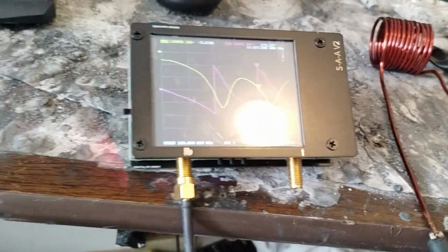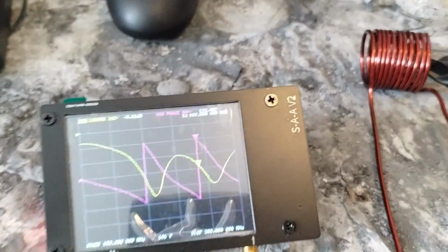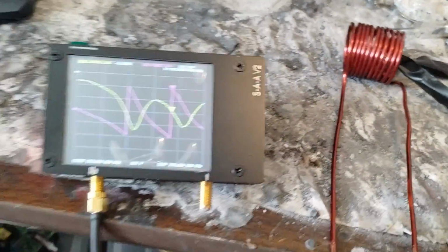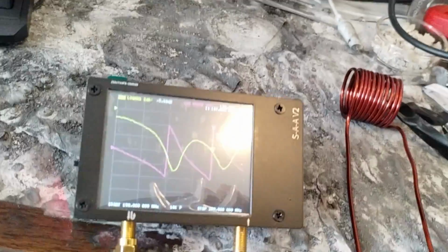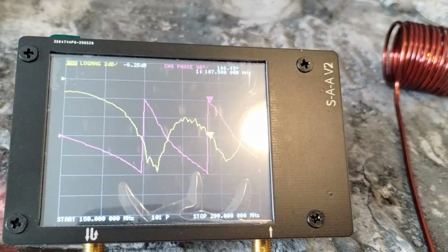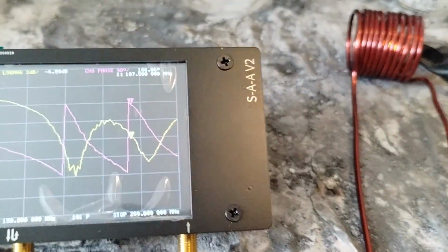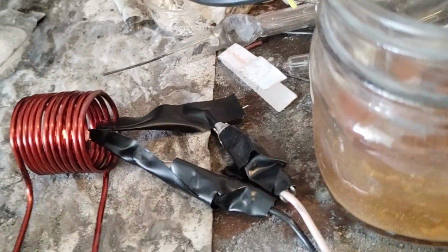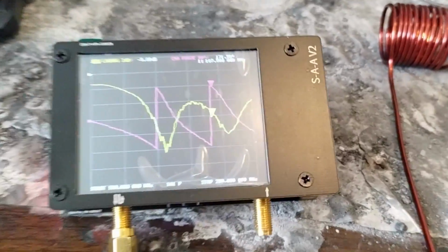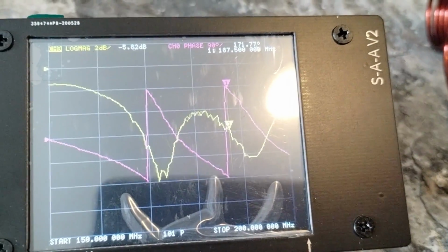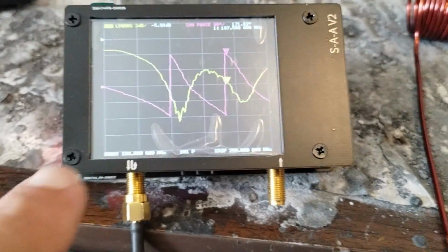Okay, so let's try flipping the power on and off. Right now the power is off. Okay, we'll flip the power on. You can see that there are ripples generated. It is a 60 hertz signal going to the light bulb. You see the light bulb is on. And so in this range we are generating a plasma that is affecting the phase. The purple trace is the phase.